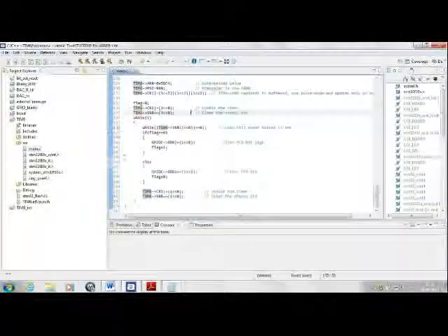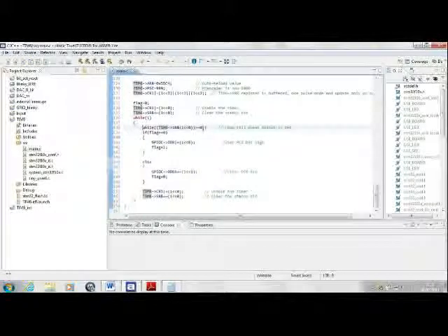And now we come to the main logic of while 1. In the while 1 loop, the very first line waits till the status register's 0th bit, that is the actual status of overflow, becomes 1. So we poll till this bit is 0, staying in this while loop, and this while loop has a semicolon, so the program will not fall through as long as the status bit is 0. Next, if the timer runs out, we fall through and execute the if else statement.